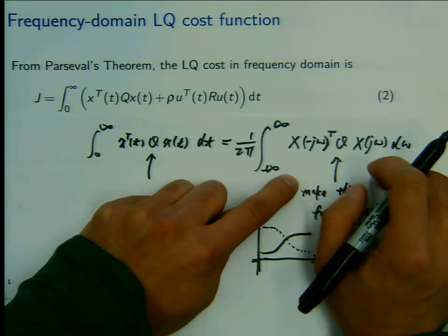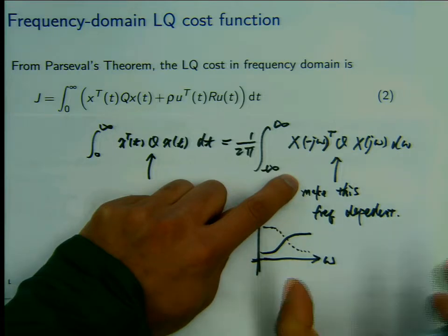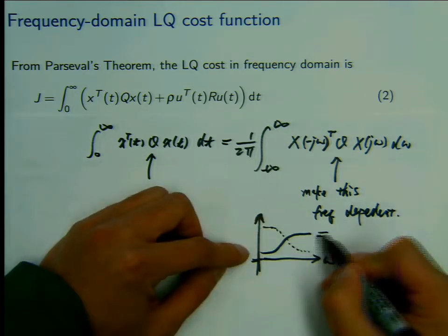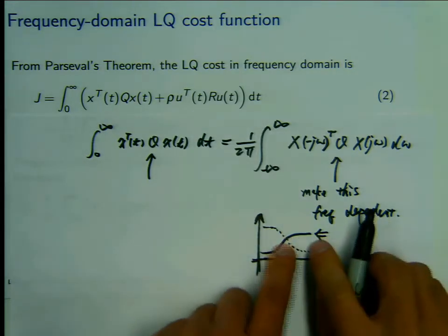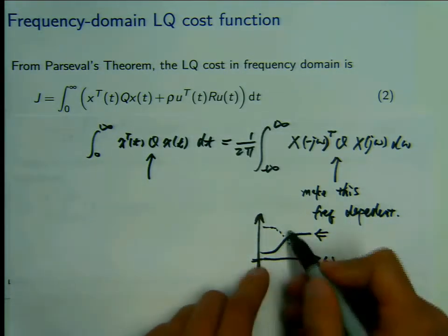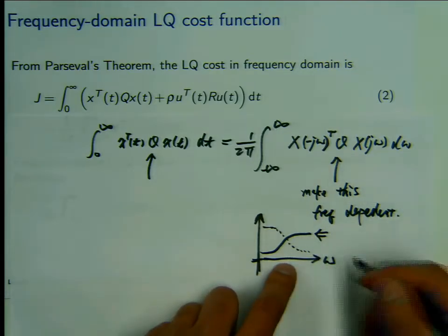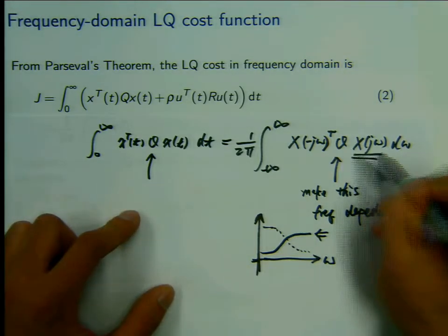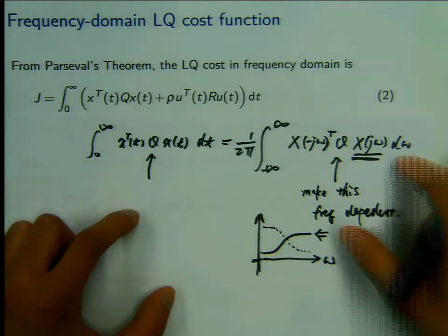cost function, then I should emphasize to minimize this part of the frequency component. So if you choose, for example, if you choose the low pass, if you choose this way, that means, okay, I want to focus on the high frequency region. The low frequency errors doesn't make much count in this case. Make sense? So now you see, immediately we are exactly building the frequency domain design intuitions in this cost function.